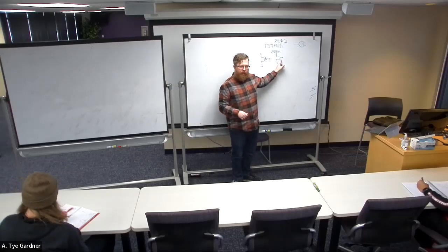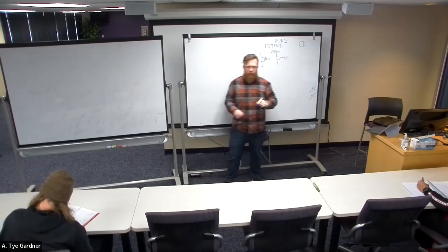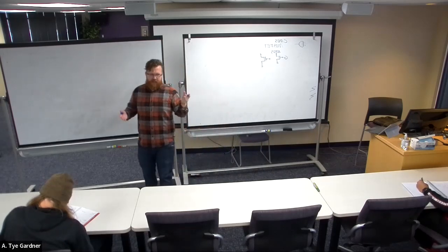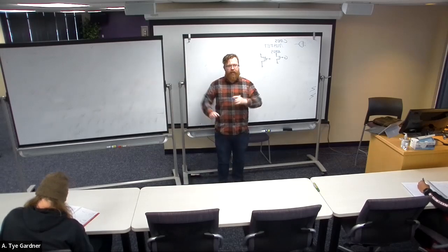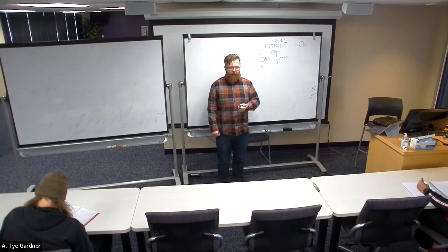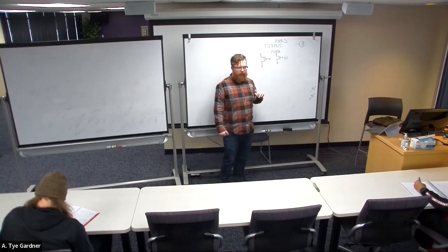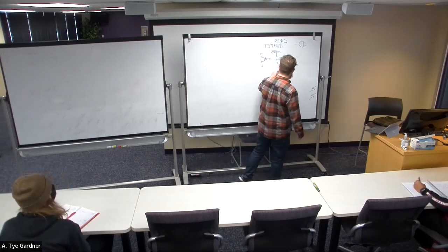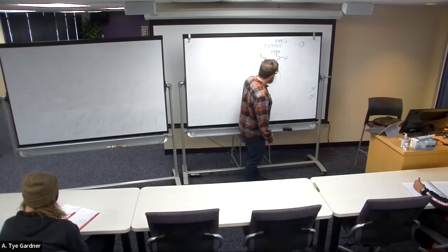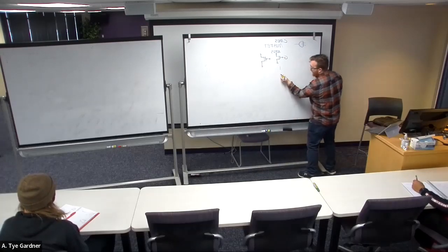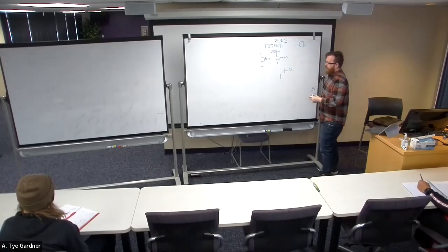This port is called the gate. And it's called the gate because it allows current to flow between the other 2 terminals. That's all it does. If it is a 1, the NMOS opens. If it's a 0, the NMOS closes. So you've got to think about it like a switch. Let me draw this the weird way, actually. I'm going to do the switch the opposite direction from how I usually do. It looks like this. That's the gate.